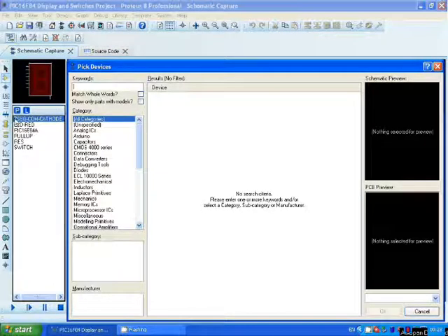And what you're looking for is this 7-segment common cathode. So if you type that name in here, you will find it, okay? So type that name that I've highlighted in blue here in the keywords, and you'll find your 7-segment display. You should already have your red LEDs, your PIC16F84, your pull-up resistors, your ordinary resistors, and your switches on your design sheet. Okay? So the only one you need to get is this 7-segment common cathode. Okay? So we'll type that in.